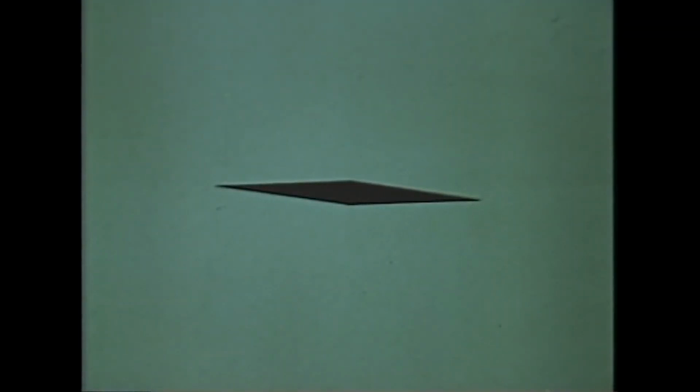In supersonic flight, the air flowing past every part of the aircraft is supersonic and behaves quite differently from subsonic airflow. Here's a section of a supersonic wing. The sudden corner on it couldn't be used on a subsonic wing, for, as the smoke shows here, subsonic airflow becomes turbulent and confused past the corner.